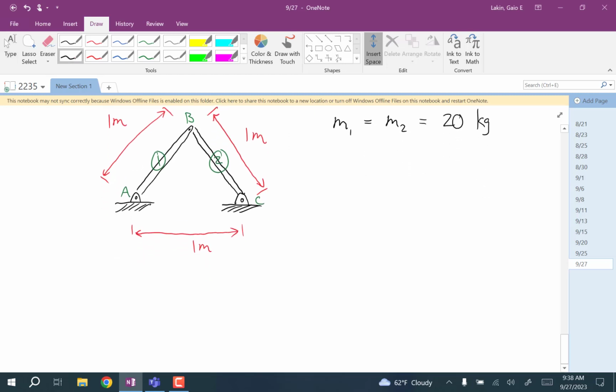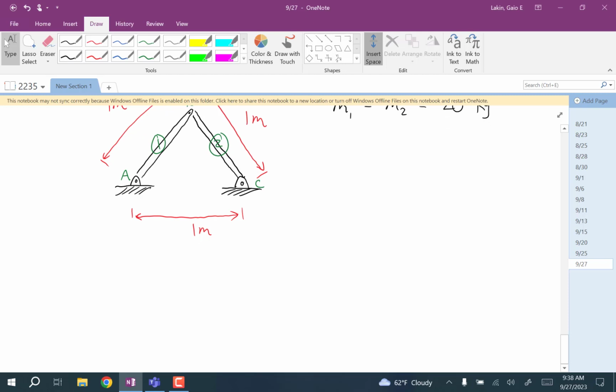Okay, one by one, I'm going to do a rigid body analysis on each of the two bodies. And then as needed, I'm going to isolate the pins and do a particle analysis. And I'm just going to keep doing this until the number of equations catches up with the number of variables. I mean, you're seeing it for the first time, so to you, reasonably, you'd just be hoping that eventually you do get the equations to catch up. So, all right, so the first one is